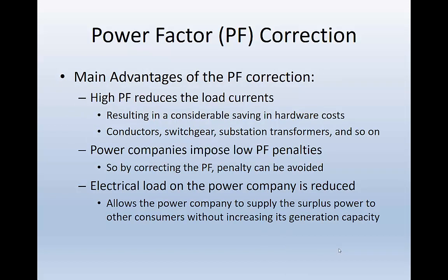One of the main advantages of doing power factor corrections in terms of how we bill is the fact that high power factors, meaning getting closer to a 1.0 or 100%, help lower the amount of energy you're using to do the same amount of work. It also means that your equipment isn't straining as hard, it's not generating as much heat. If you do have low power factors on your equipment, it is possible the utility company could actually bill you at a higher rate than they would a company with a much higher power factor. Okay.